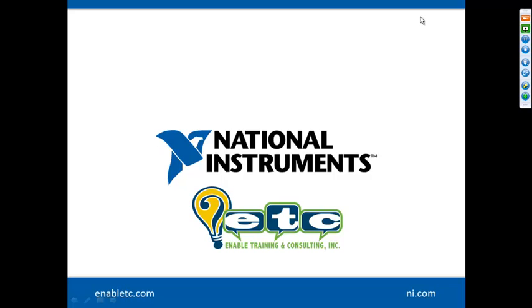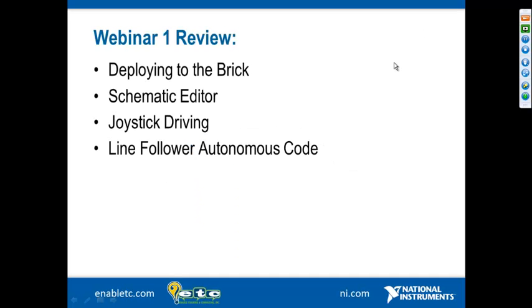What we're going to talk about in this one, we're going to begin with just a quick review of what we covered in the first webinar. In particular, we're going to talk about how to deploy to the brick, the schematic editor, joystick driving. We're going to do a very quick summary of the code that we developed in the first webinar. And then we're going to move on to create some slightly more complicated code for a more sophisticated robot, where we've taken a simple bot that was used behind the scenes for the first webinar, which has just got simple DC motors to left and right wheels to drive, and a light sensor and an ultrasonic sensor, to add to that servo motors and the ability to drive them and make autonomous decisions based on what you see there.